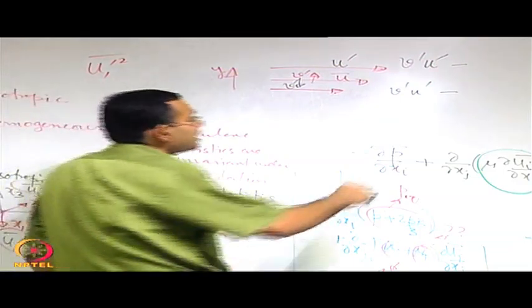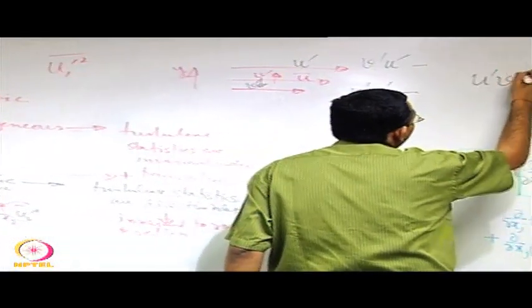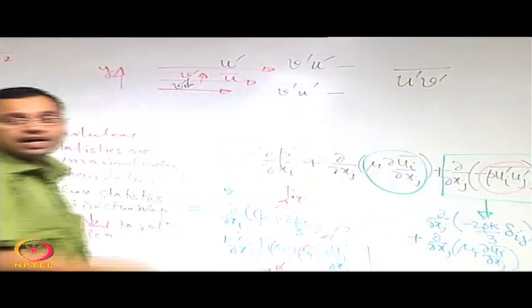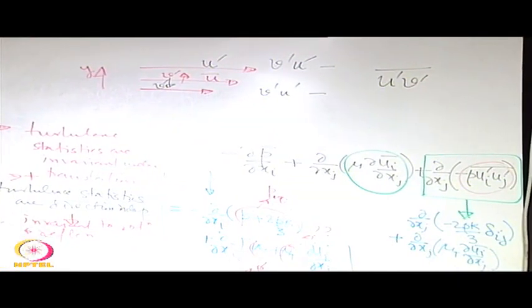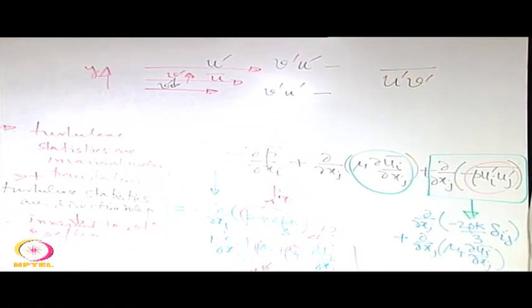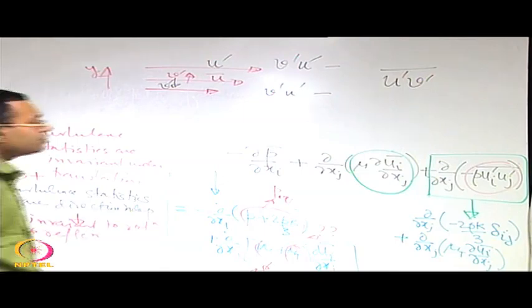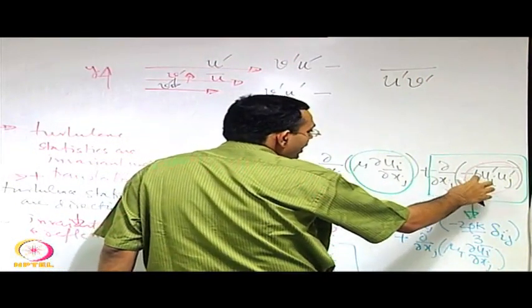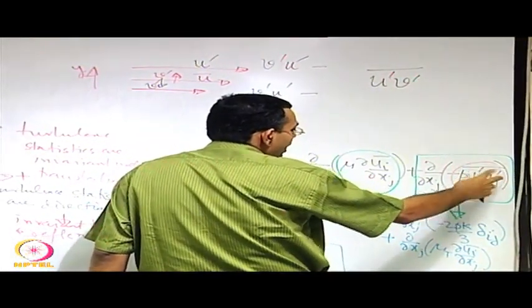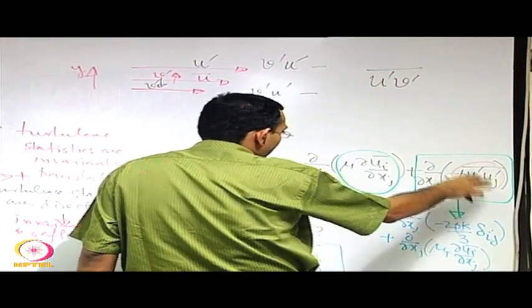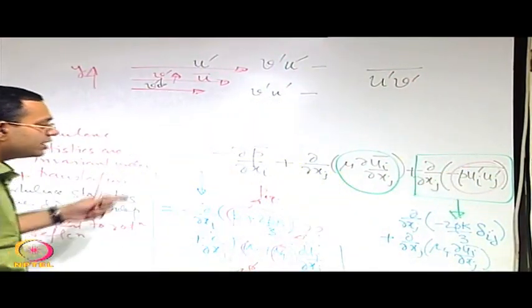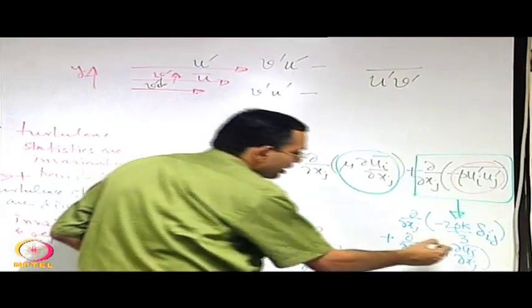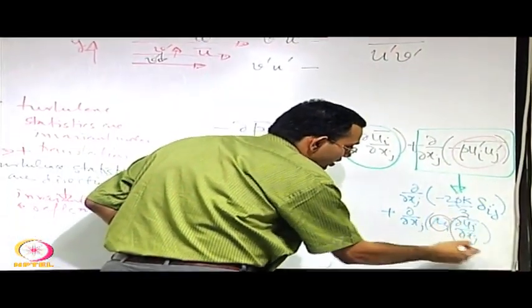Therefore we can say that when you statistically average this u prime v prime, all the negatives add together and the statistical average is not 0 in general. So that is why, when we wrote minus ui prime uj prime when i not equal to j, meaning the deviatoric component, we wrote it in the form of mu t into this velocity gradient.